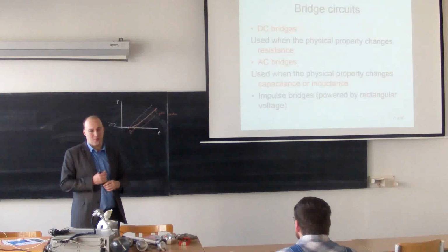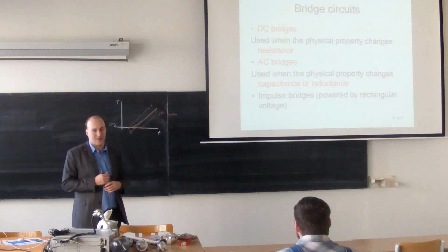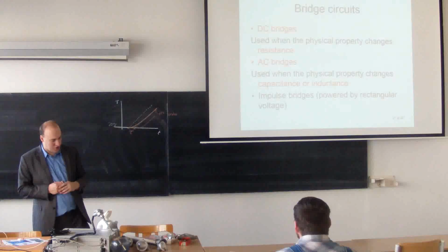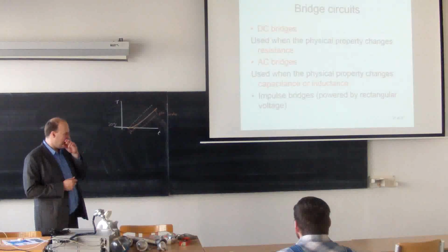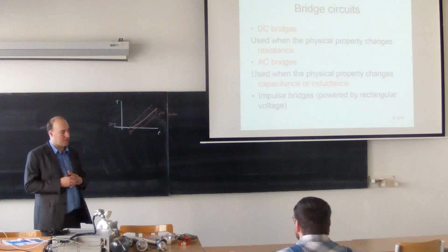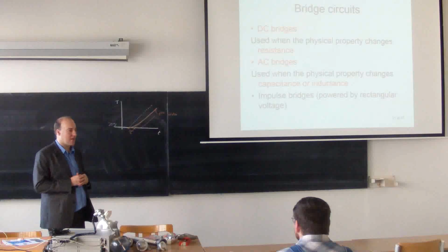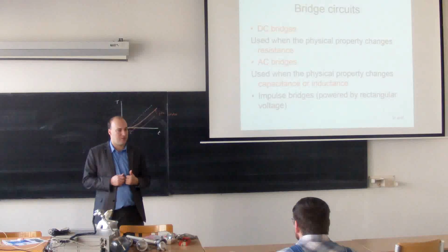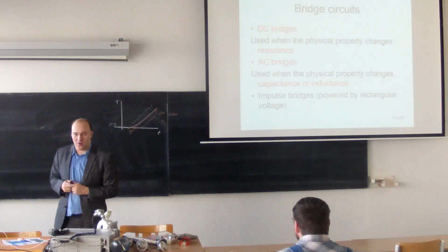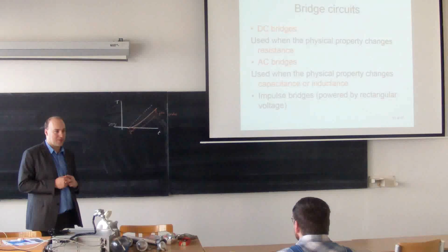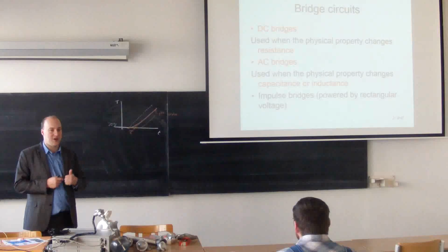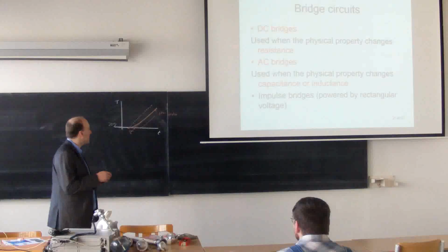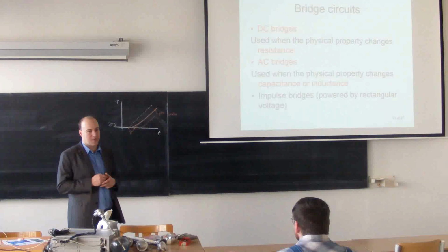Have you heard about a Wheatstone Bridge? Okay, so we're going to use a Wheatstone Bridge for this function. If you look at the bridge from the power supply side, the bridge can be supplied either by DC voltage, AC voltage, or some impulse voltage. So this will give us a DC bridge, an AC bridge, and an impulse bridge. We will discuss only the first one, the DC bridges.